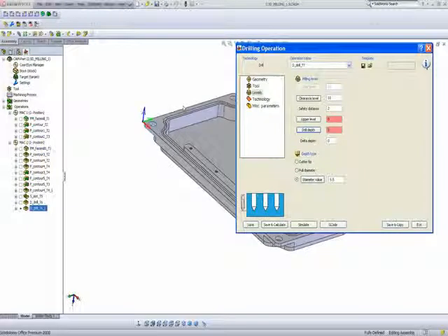So what I'll do is in my levels area, I'll use what they call full diameter. Notice I want the full diameter of the tool to get to the bottom. If I want, I can even go a touch deeper than that. And I can say over here -1. And all of a sudden the tool will even go past that area by 1 millimeter.